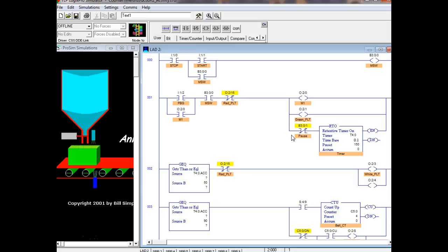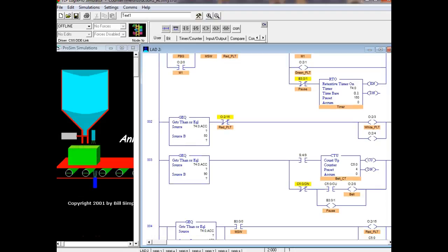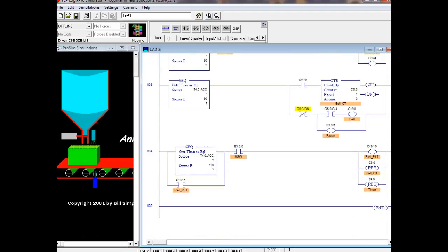Some of y'all use more than that. The problem you have is down there, we try to make that light ring. I'm using that S4 register that we talked about. That automatically gives you a count. That's the one I was using, which saved me a couple of rungs. But this program is 5 rungs.